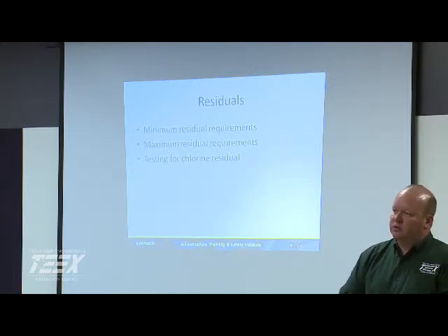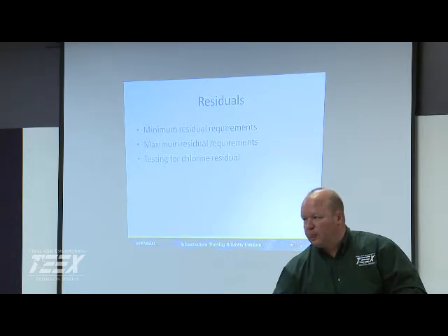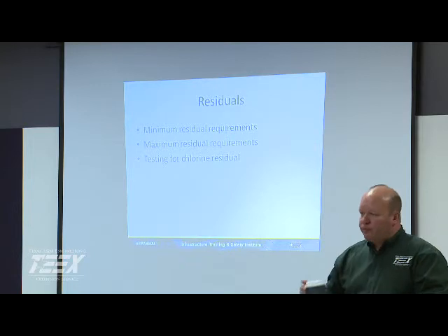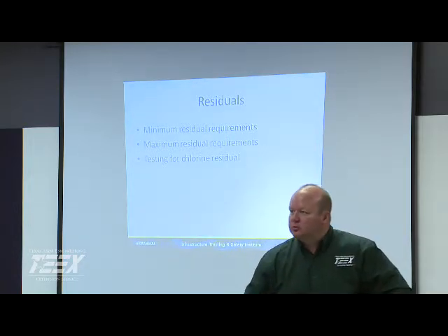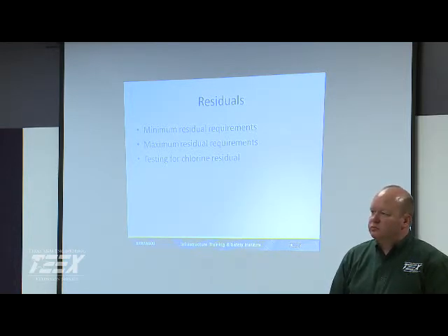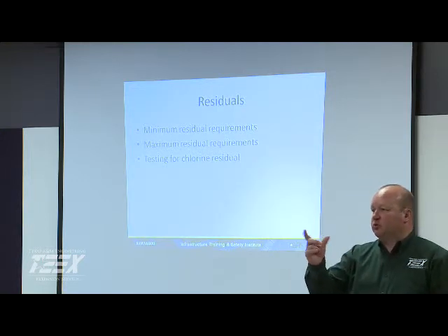Okay. And then on the handhelds or the benchtop instruments for the chlorine, it's usually whenever Labtronics, a lab certification company, comes in, they'll do, I guess, a calibration. But what we've been told is that, especially on those handheld digitals, you have to send it back to Hawk for recalibration. You can check it with the standards, but to actually do that calibration, you have to send it back to Hawk. All you can do is verify the accuracy off of a known standard.